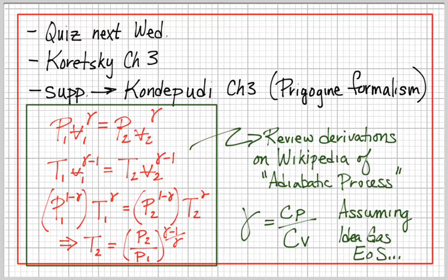Last note on the adiabatic processes is that we're familiar with an adiabatic process as PV to the gamma equal to a constant. When we solve problems for that, we set PV for state 1 on one side and PV for state 2 on the other side of the equation. What you're seeing here is just if I were to use the ideal gas equation of state, PV bar is equal to RT, I could swap out any number of those variables, just like TV bar to the gamma minus 1 is equal to TV bar to the gamma minus 2.